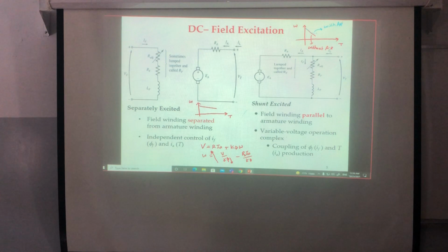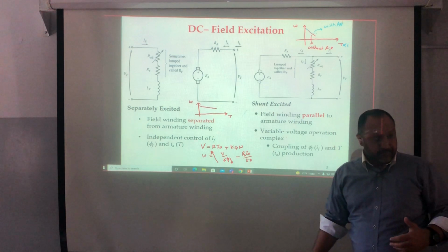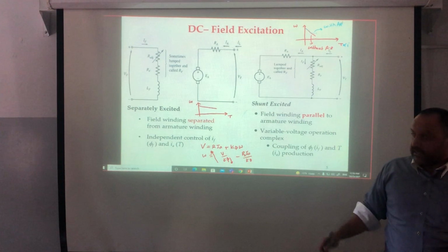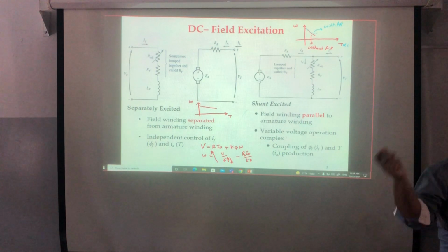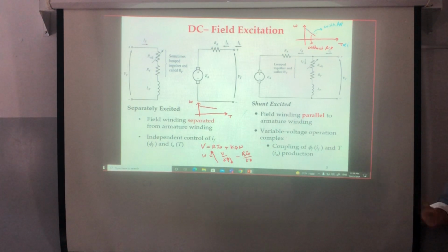Simply, if you notice here, while the torque is small, the current is small. So it will generate a small flux that will never interfere with the main flux. While I'm increasing the torque, because you know that I can plot this with the current I, this is what we call the electromechanical characteristic. The current with the speed is that, and the torque with the speed we call the torque speed characteristic, or the mechanical characteristic.